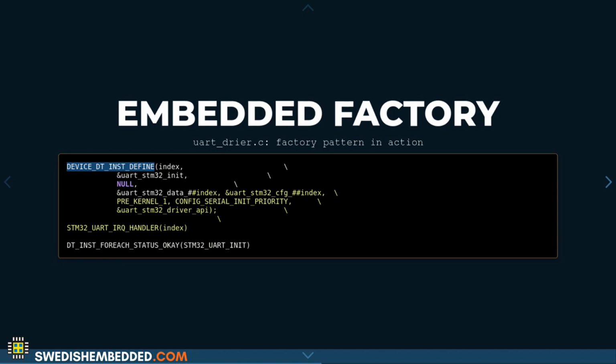You need to actually call the GCC function that goes through this list and calls all of the constructors. But the concept is basically the same. And this is embedded into the executable. So that could be another way of relating to the name embedded factory. It's often very hidden and just handled by the startup code before your application even starts.